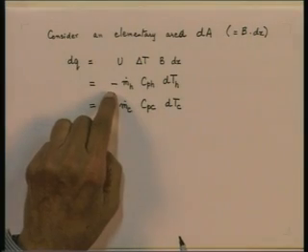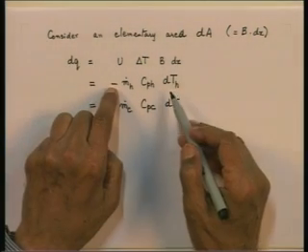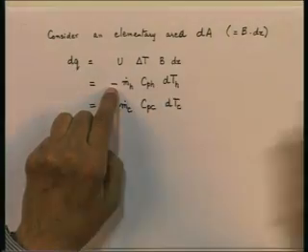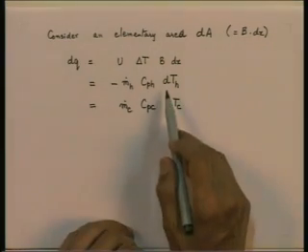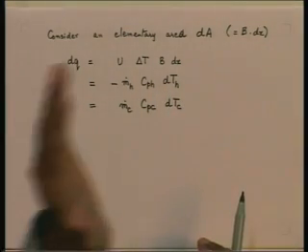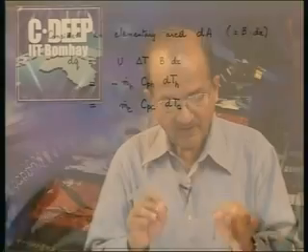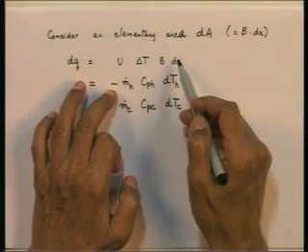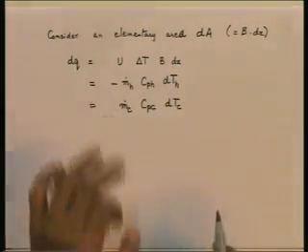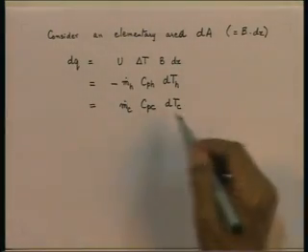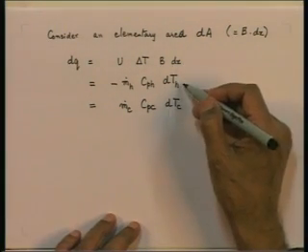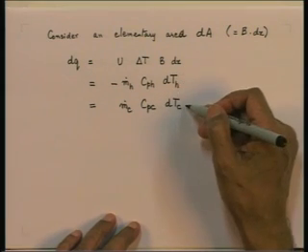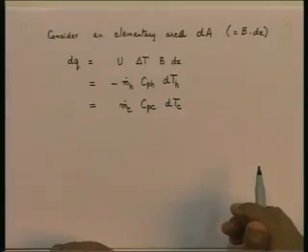Notice I put a negative sign on the dTh on this first one. Why? Because dTh will be negative in the positive direction, which I am measuring from the inlet. X is being measured from the inlet. So, the temperature of the hot side will go on decreasing in the positive direction. dTh will be a negative number. So, I need to put a negative sign in order to get an enthalpy change and equate this to the heat transfer rate across the area dA. So, these are all equal expressions. This is the heat transfer rate across the area dA, this is the enthalpy change on the hot side, this is the enthalpy change on the cold side, and they have to be all equal.